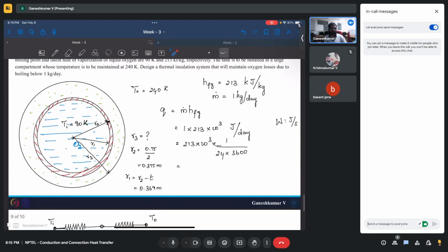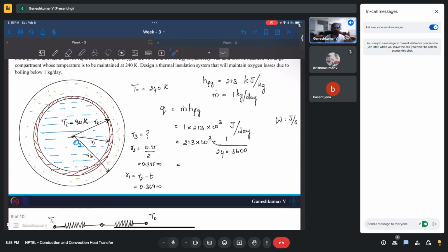Also, in a space shuttle you do not have gravity, so unless you blow the air through a fan, you will not have convection. Free convection will not happen in space because we do not have gravity, so we will not have circulation of air. Gravity and buoyancy is what makes hot air rise up and cold air come down.